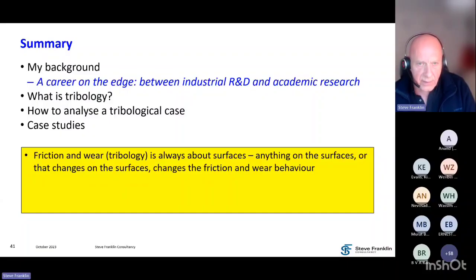Just to summarize, friction and wear is always about surfaces. That's an important thing to remember. Anything on the surfaces, or that changes on the surfaces, changes the friction and wear behavior, and that means you can use coatings and surface treatments very effectively in tribology.